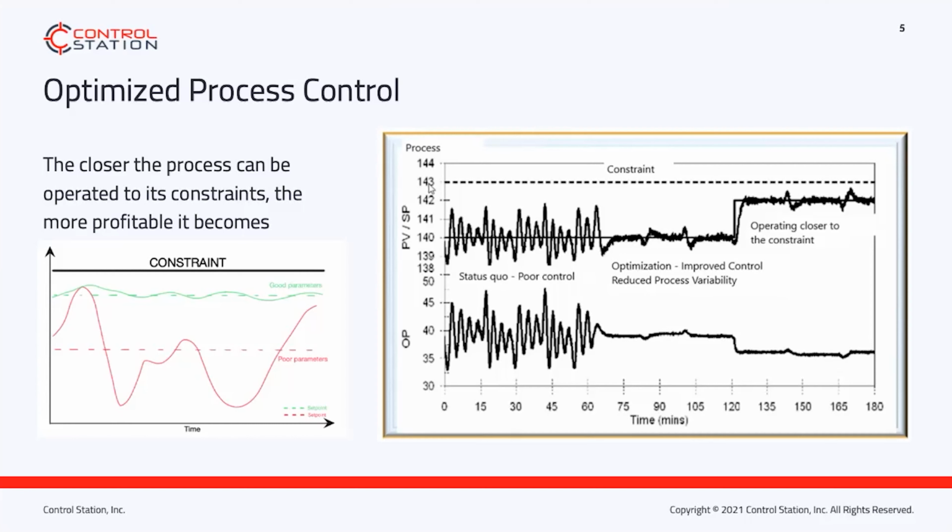So what do I mean by optimizing a process control system? Generally, it is difficult to define the optimality of a controller, as there are many important aspects to take into consideration, such as set point response, disturbance rejection, robustness, input usage, and noise sensitivity.